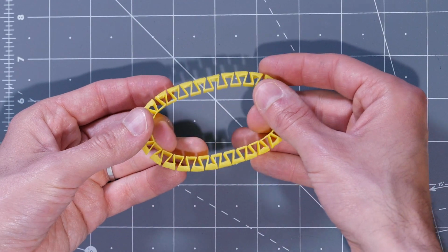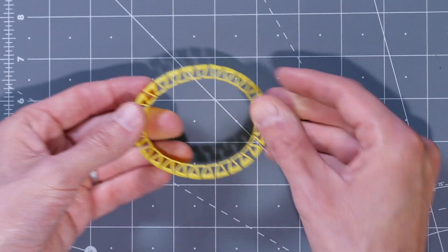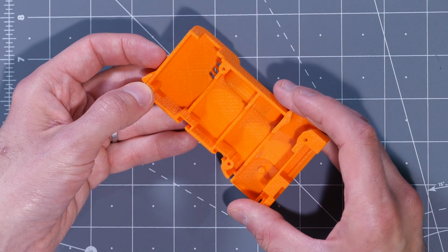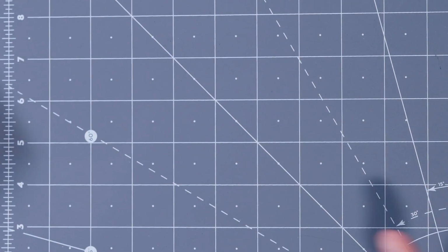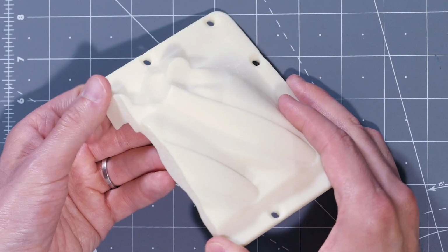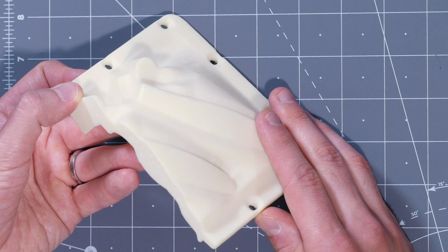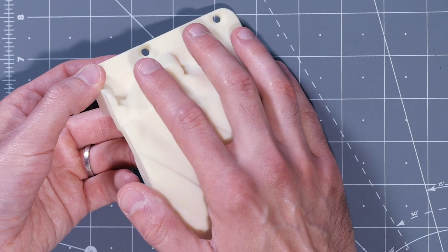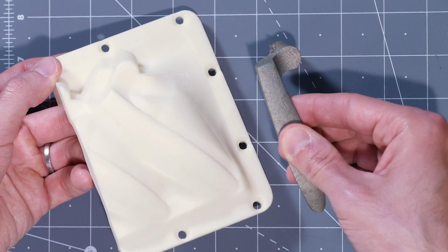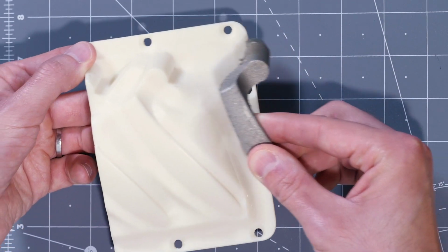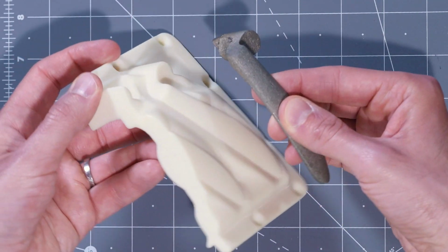Applications of extrusion AM range from small to large, simple to complex. For example, articles of personal fabrication, like this flexible bracelet, or complex housings, used in this case for prototyping of an electromechanical device. Extrusion AM is also used widely to make tooling, jigs and fixtures, and mold tooling. This piece of mold tooling is used in sand casting. The tool is 3D printed, and then sand is formed around its shape. And then the 3D printed piece is removed, and molten metal is poured into the sand form to produce this part. So the finished part matches the 3D printed tool with an offset due to its thickness.